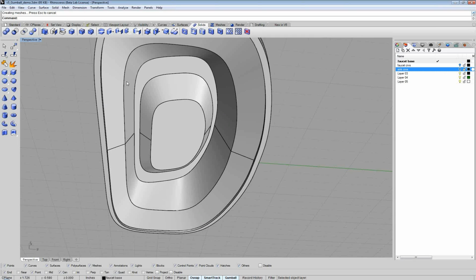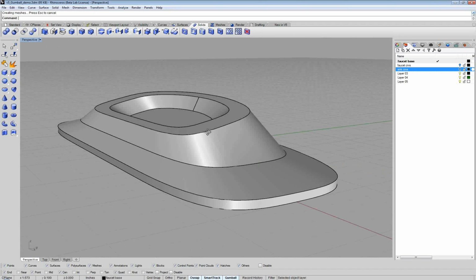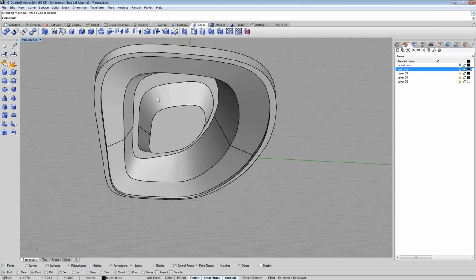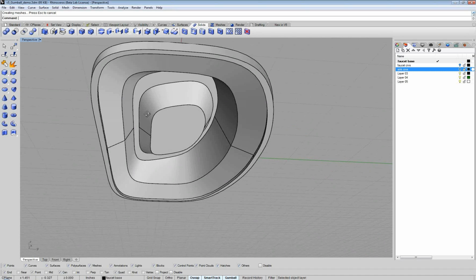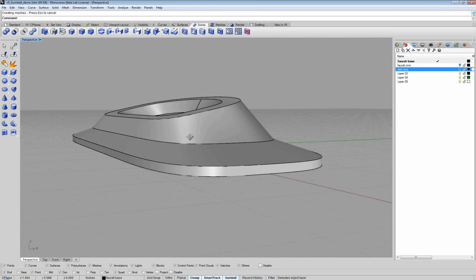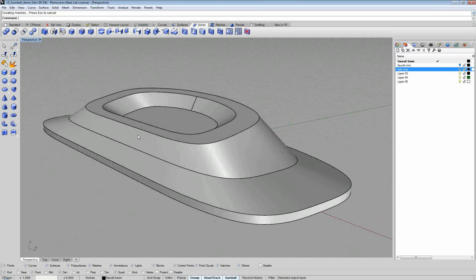Personally, I like to create these B-side surfaces before any fillets or blends occur on these top edges. The results are going to be more consistent, and we also don't really need as much curvature on the underside here. It keeps it much simpler, and so your results are much faster to calculate as well. So I have a shell thickness now, and now I'd like to beautify the top here. I'd like to make this transition between these sharp edges much rounder. I'm envisioning this design as being maybe milled and polished out of marble at the moment.